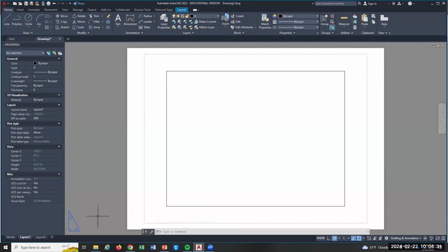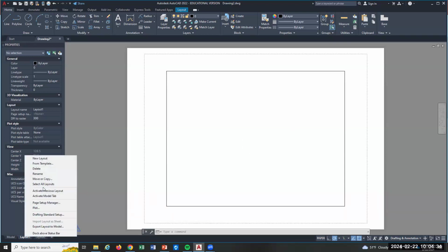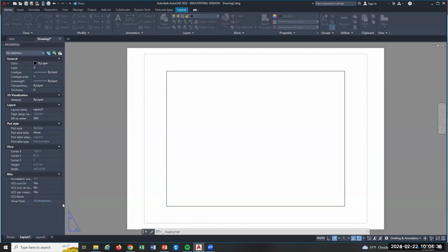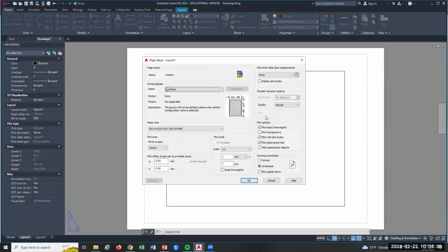So what I suggest is you actually change them both by doing your page setup manager, modify, and get rid of this ISO A4 size paper, because that printer actually won't understand it. If I go to print it, it'll be like, what the hell's that, right? So even in the metric version, you might want to set it up to like an ANSI style piece of paper, because it will understand that. A size is the 8.5 by 11. B size is the 11 by 17. Okay.